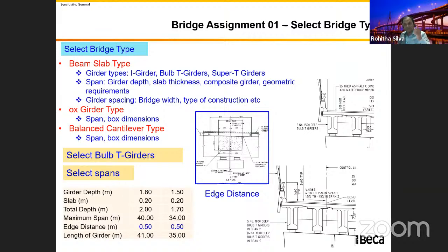So you need to have a reason for the client, because safety first. And in this valley, you can't build this one. The construction cost is higher. If you use temporary form, how are you going to support it? It's in a valley on this slope. How are you going to work? You need to put this argument in front of them. You need to justify your answer. You don't have to justify the bridge width, because that's a given. You have to follow that. That's a requirement. But here, you are selecting, so you need to justify.